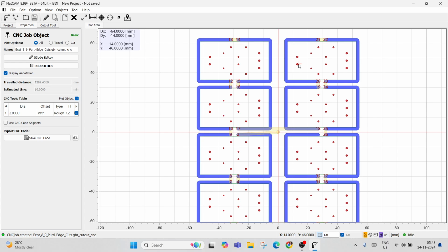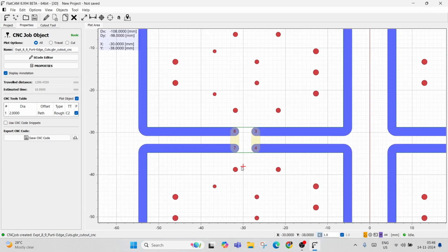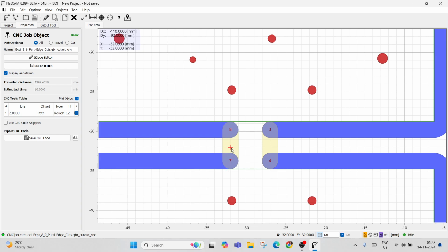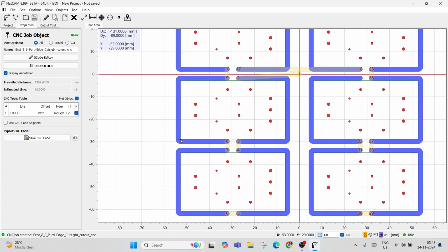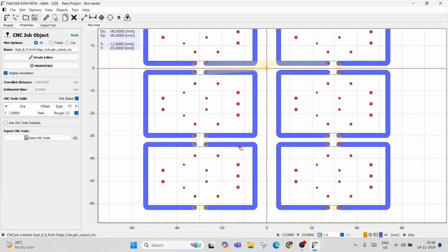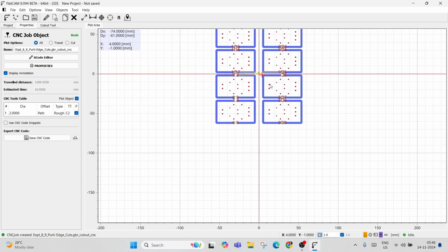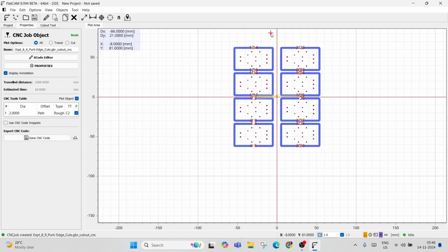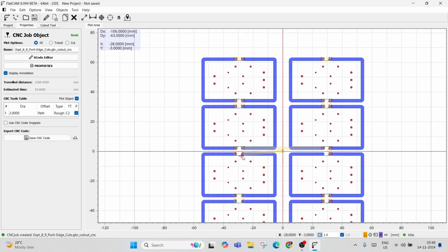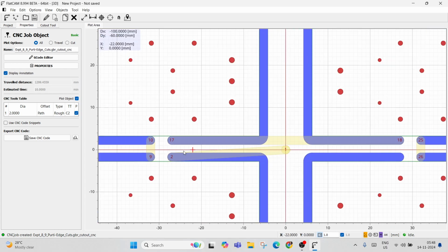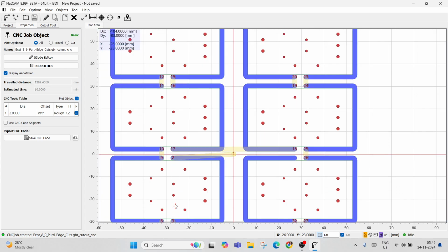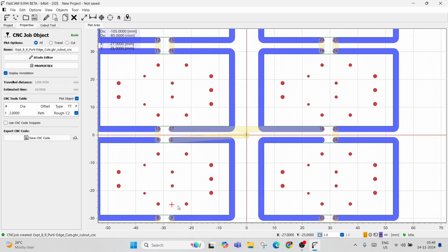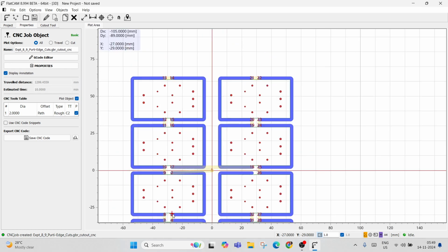As you can see, this is the CNC job. What you can see over here are yellow places where travel Z will happen, which means it is going to be traveling, not drilling. And blue lines are the places where it is actually going to be performing the drilling. So you can see it is going to start, where is one, this is two. It starts from the origin, one, then it will go to two, then three here. You can't see the yellow lines here, anyway, then it is going to go to 3, then to 4. It has its own algorithm.